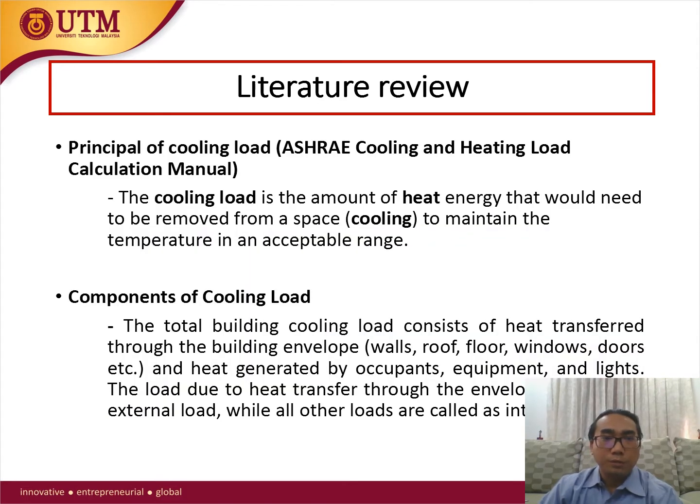Principle of cooling load. The cooling load is the amount of heat energy that needs to be removed from a space to maintain the temperature in an acceptable range. Components of cooling load. The total building cooling load consists of heat transferred through the building envelope, such as walls, roof, floors, windows, doors, etc., and heat generated by equipment and lights. The load due to heat transfer through the envelope is called external load, while all other loads are called internal load.